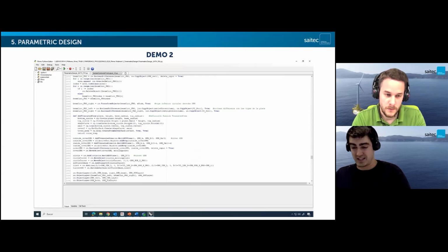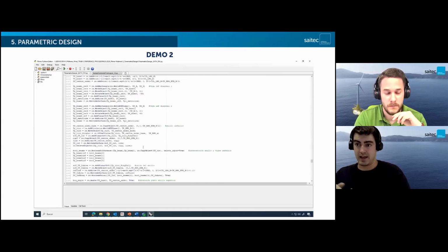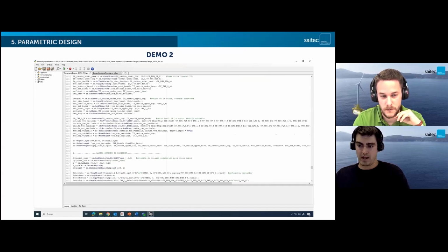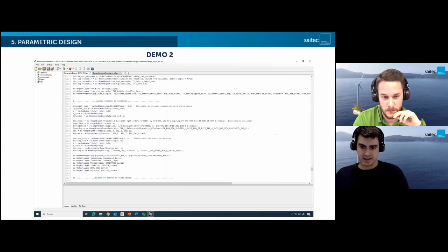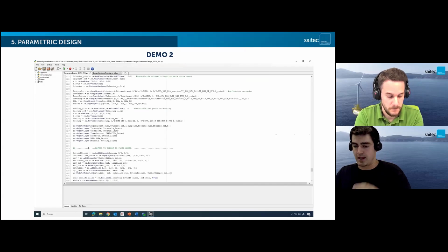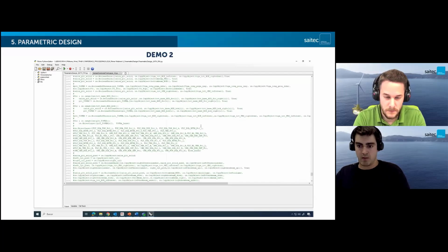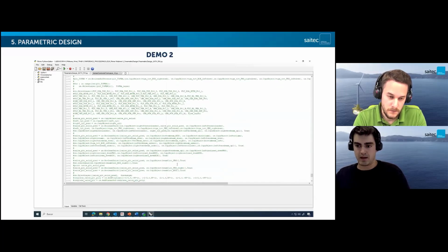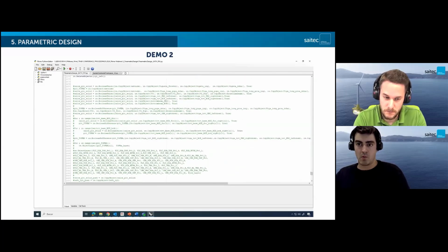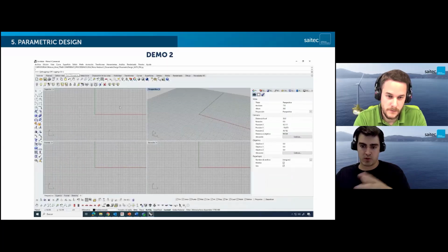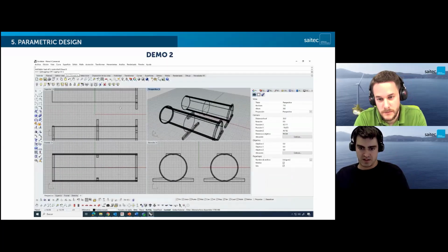That usually is the one that is more difficult to model, as they have a lot of intersections between beams. Then the transition piece. We also have the tower, and the layers defined by position, such as the mooring or the turbine. We don't model the turbines or the mooring system. We put a closed polysurface like a basic one, then we associate a density, and finally we have the panel model that we export to IRD and the Morrison elements.